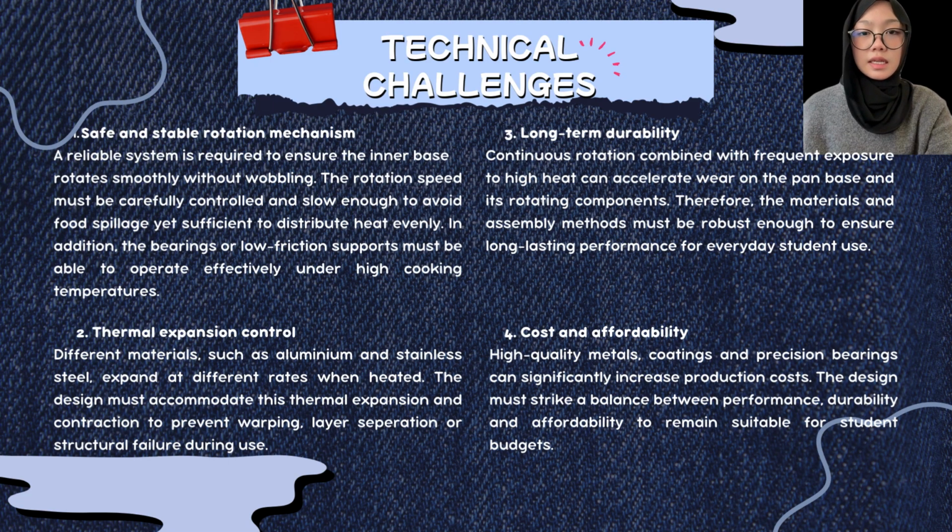The second technical challenge is thermal expansion control. Different materials such as aluminum and stainless steel expand at different rates when heated. The design must accommodate this thermal expansion and contraction to prevent warping, layer separation, or structural failure during use.